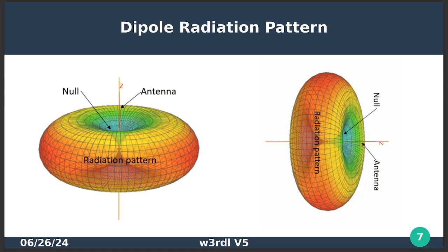So I had all that in my mind. I was really going. I thought I had this whipped on the first try. Cut it in the wrong place. And then ended up with the gap. There has to be a gap between the radiating side and the matching element. There has to be a 0.81 inch gap. And I cut it on the window. And as soon as I made the first cut, I said, man, I was not supposed to do that.